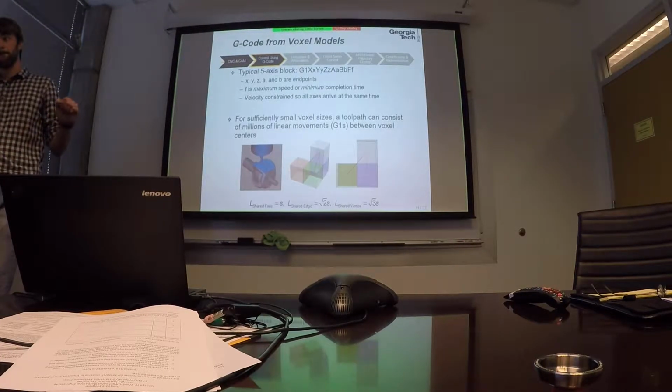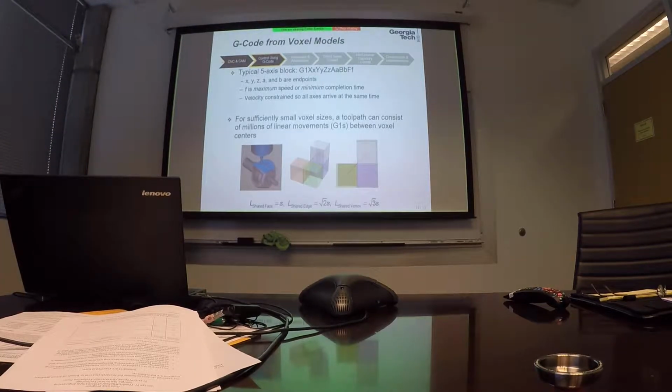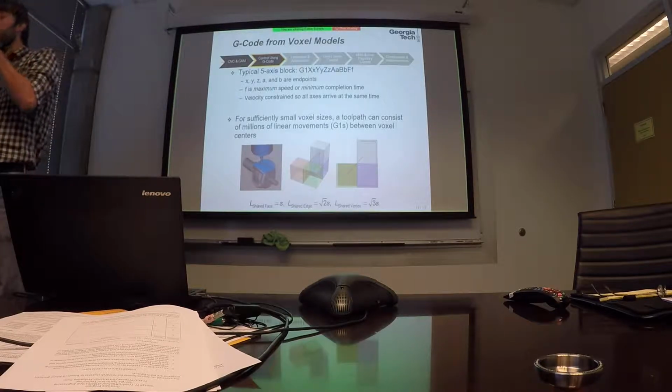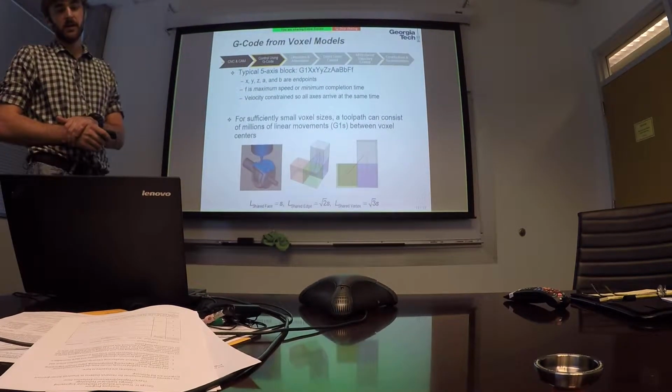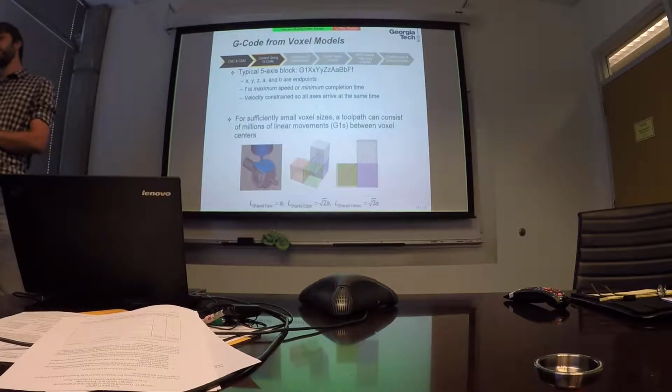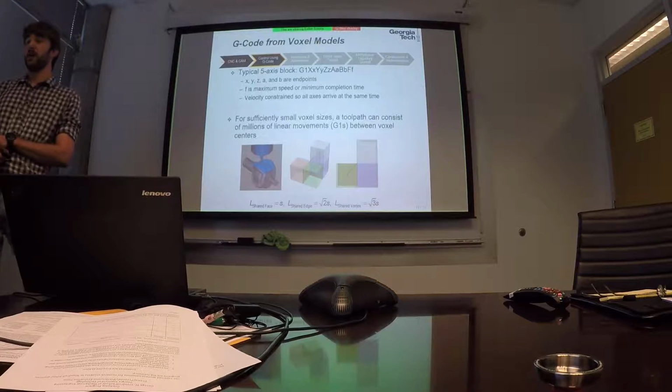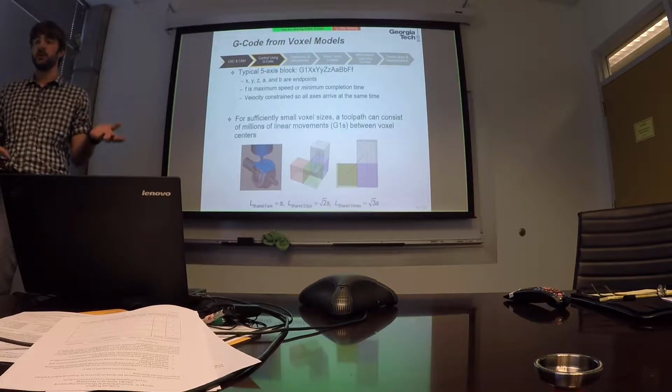So the program flow includes loops and conditionals? It can. What can you access as variables that you could use in these conditionals or loops? Positions, angle, forces, velocities? Typically, the machine will have what are called macro variables, which will be NC registers that you can store values in if you want counters or if you want timers.